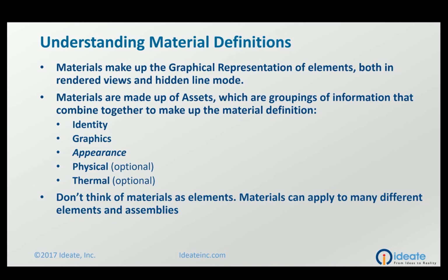So the materials in Revit make up the graphical representation, so basically when you're looking at things when you cut with a cutting plane, or when you're looking at things from a projection standpoint, right? So like if we take acoustical ceiling tile as an example, there's basically a projection for that, right? So when you look at construction documentation, it's that stippled pattern that you typically see on most of your documents. So materials, that's where all that stuff is set, right? So you make a material pattern and then you apply that pattern to that material.